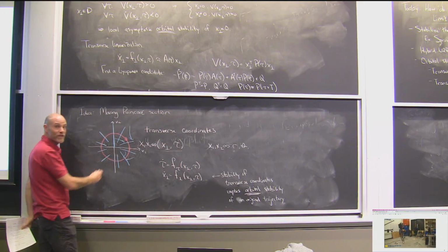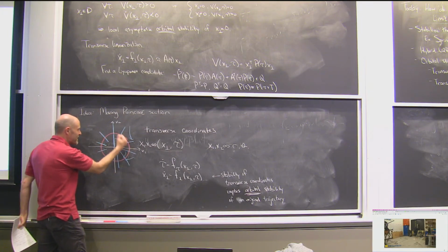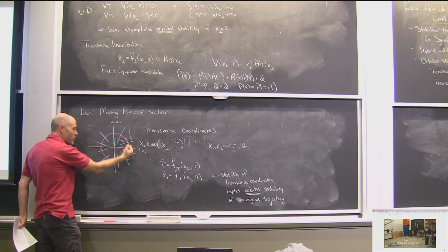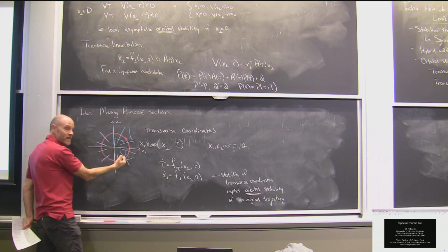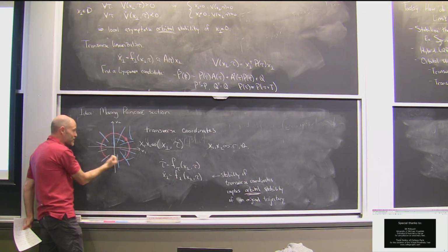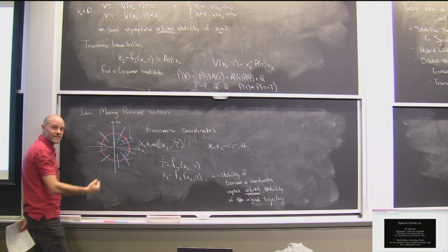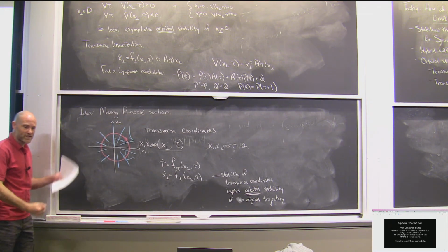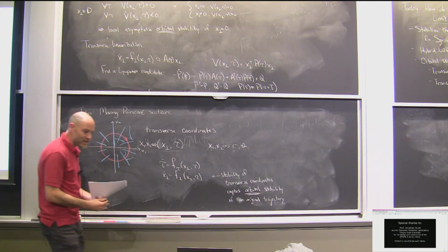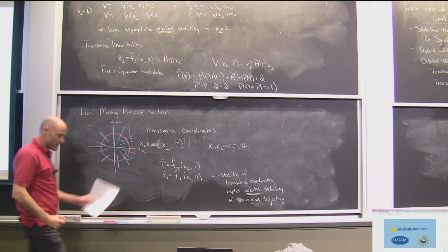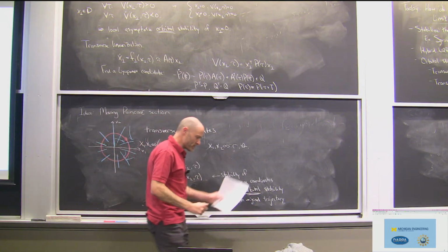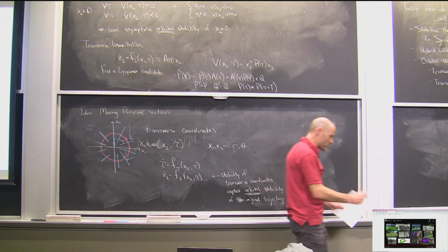So what he's doing, actually, he's just walking up. And even though the robot, by default, wants to walk forward, he's just pulling it backwards, and it's like a clockwork man, right? It's just being pulled backwards along the cycle, and it's stabilizing all the other coordinates. So it does its nominal gait, it's looking up where it is in time, it's figuring out what its other joints should be, it's just doing its good walk.